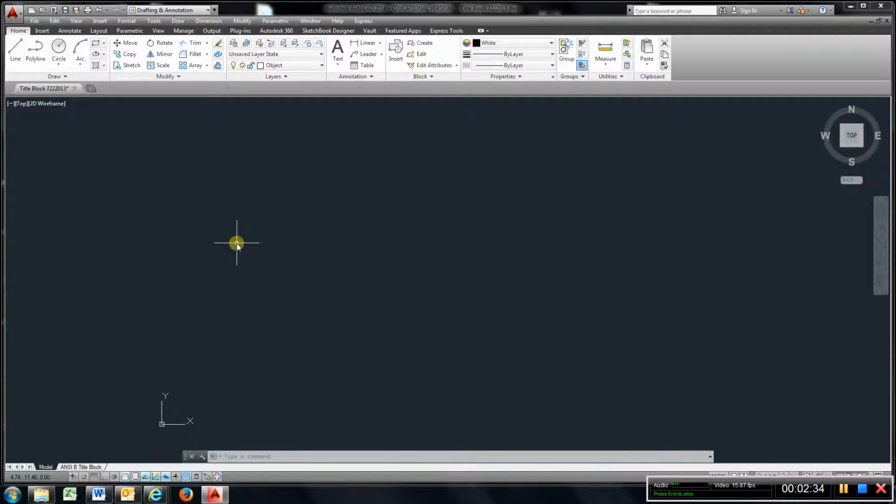Okay, looking at the T-clip, I have a line that's 6.5 across the top. A couple things I want to do here. I want to turn on ortho. Ortho, you can only draw up, down, left, or right. And I'm also going to turn on dynamic input. Okay, so I'm going to turn ortho back off and use dynamic input, and I'm just going to lead it in the direction I want to go. Make sure it's straight. Type in 6.5, enter.